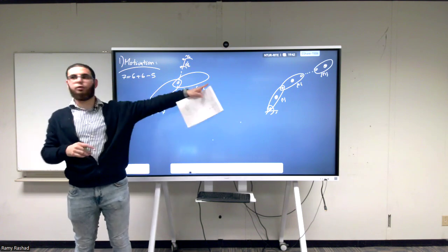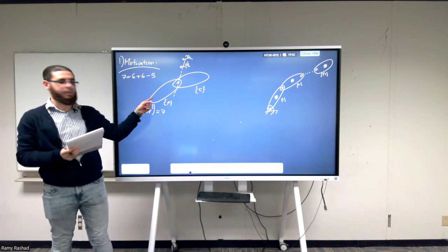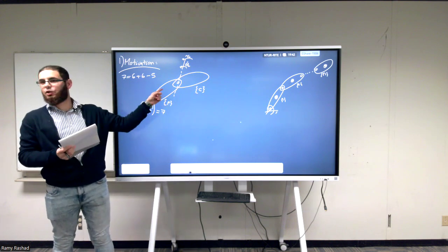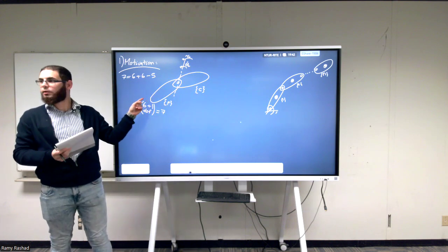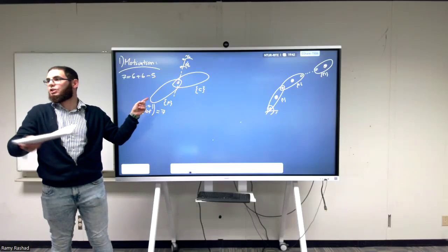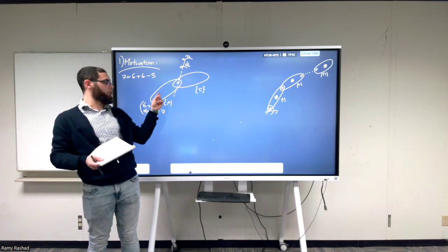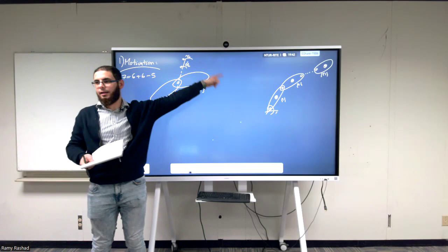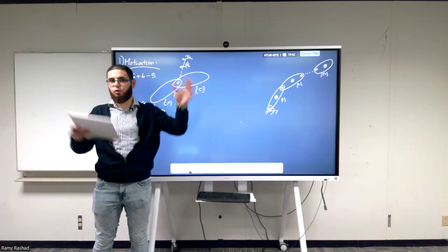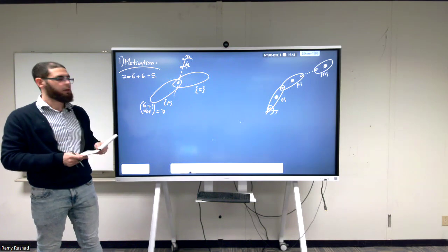How do we make this one into that one? You first connect the parent, right? Assume that this is the 0 one. We connect it here by another joint to the base space, or to the stationary frame, the base of the robot. And then you keep on adding here. So this will be link 1, this will be link 2, and then you add link 3 up to link n. Okay, so we're going to be seeing how recursively we're going to be building this in a tree model.